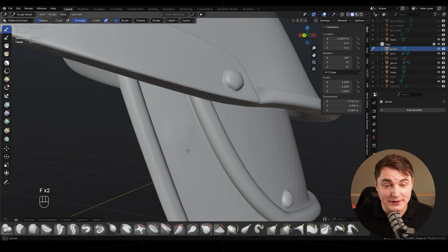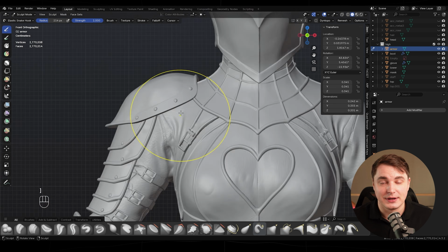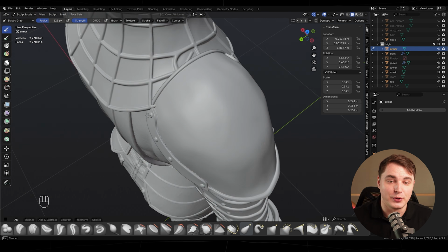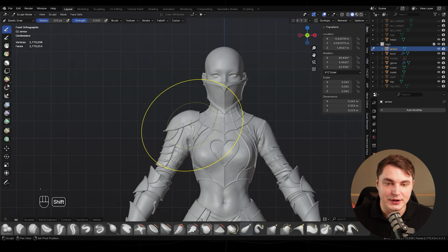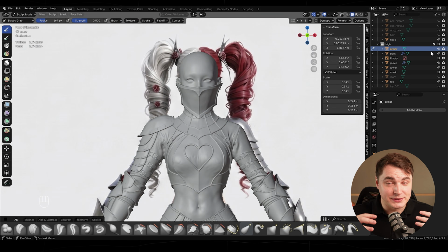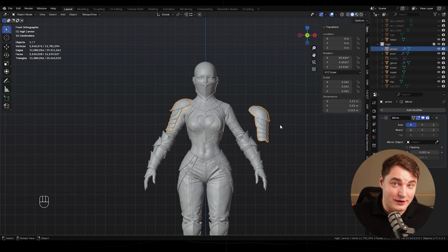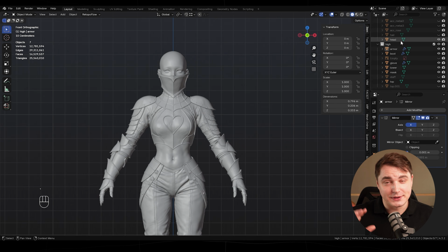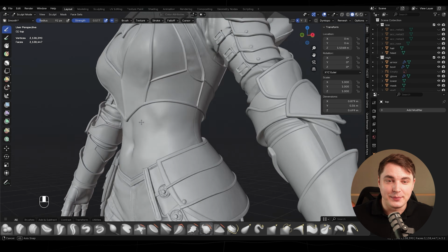Note that sculpting works pretty nice with low poly as well. Brush like Elastic Wrap is absolutely cool to use with low poly as well. But if you're gonna try other brushes such as clay or even smoothing, it might ruin the geometry because those brushes affect vertices and are designed to work with high poly meshes. In my course, I cover both approaches, what tools to use with low poly, with high poly, etc.